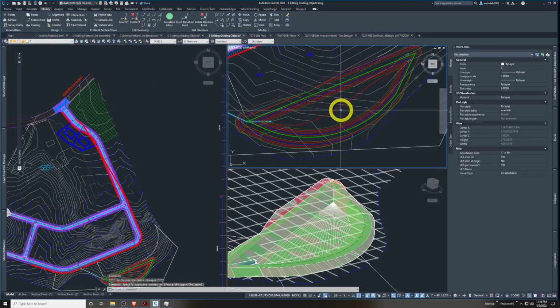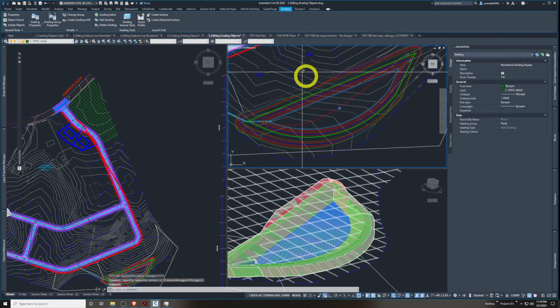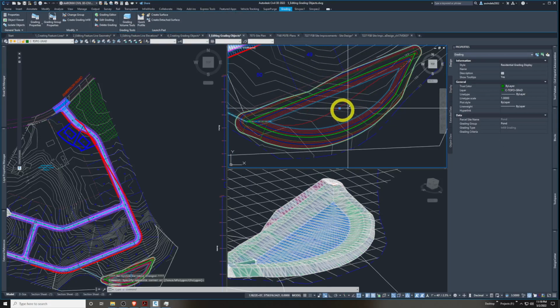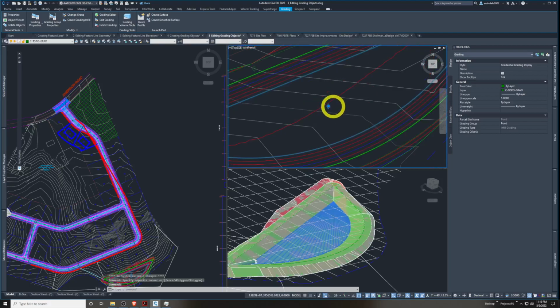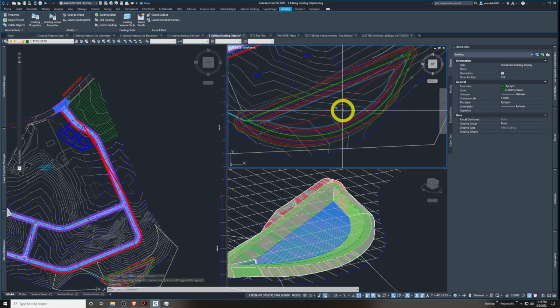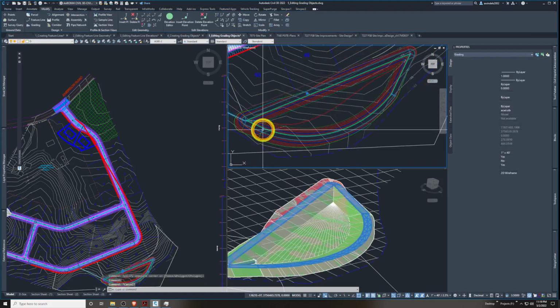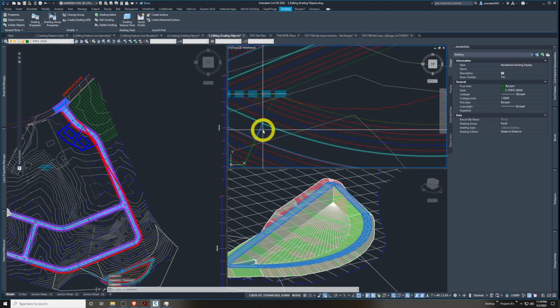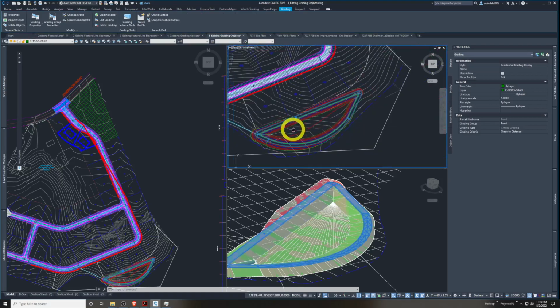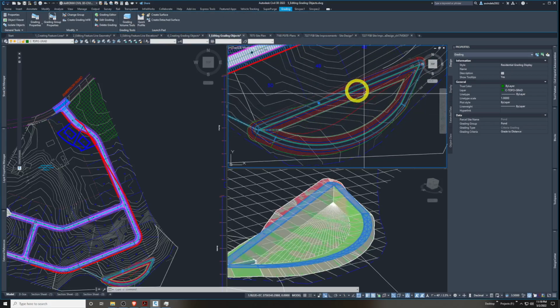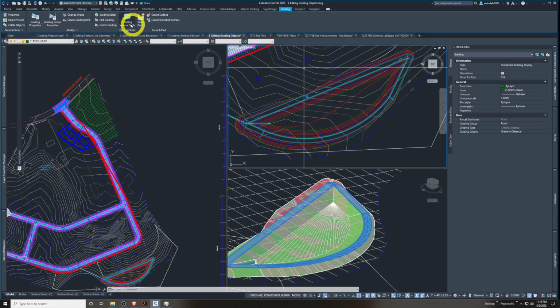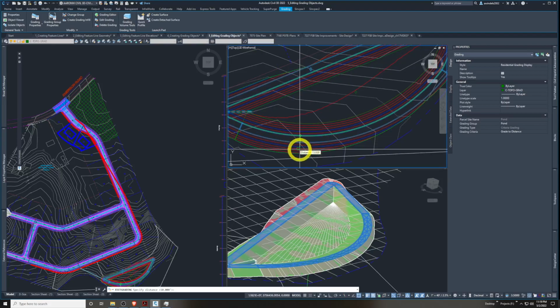So let's pick the grading object again so we can get the ribbon back in case you lost your ribbon. Pick these little diamonds is one way inside of them. Or if you hit escape and pick the sides like this where it grades, that works too. Just pick anything that you can graphically to get this contextual ribbon up. We'll hit edit grading this time. In this case, I already kind of picked an area in the top of the berm. I did 2 feet last time.